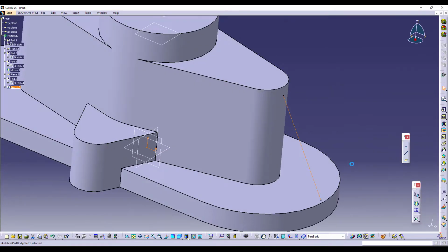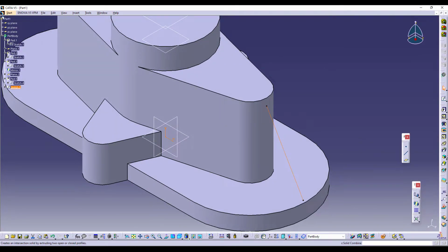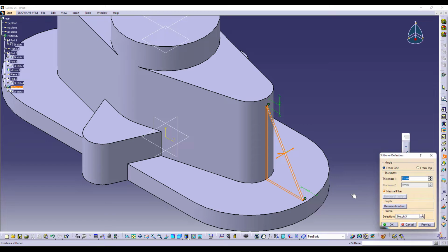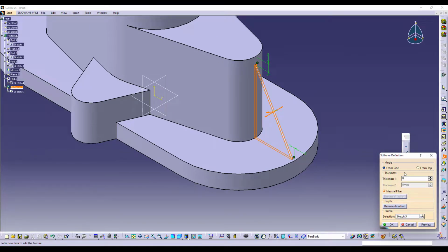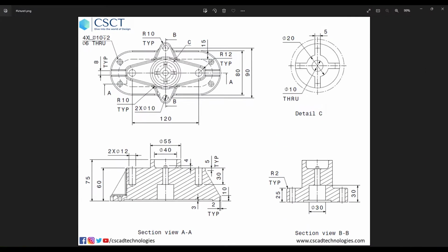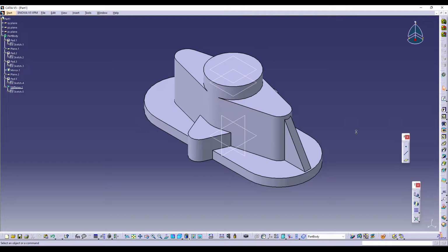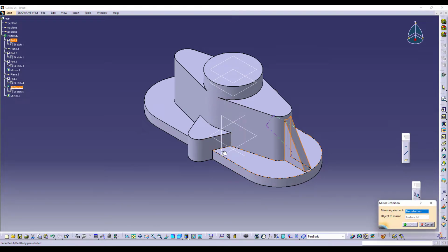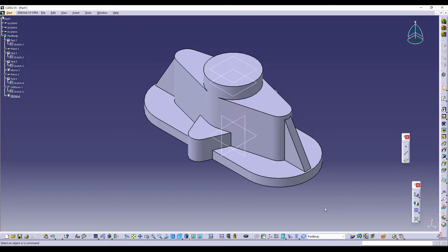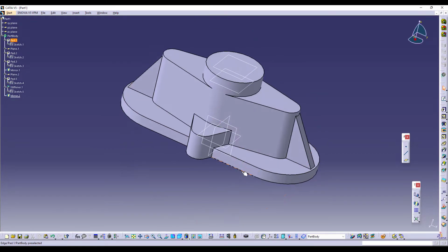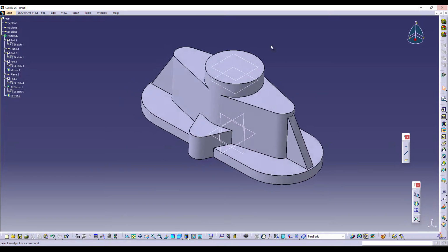Now once I exit, I'll use stiffener. Stiffener is usually used to give supports, and the thickness is 8, which again is provided in the drawing in the top view. Now since the same thing is being made on the other side, instead of redoing it, I'd like to mirror it. Let me select the stiffener first. It's actually taking stiffener as the mirror, so I'll not do that again. This is here. Now, isometric view back again.